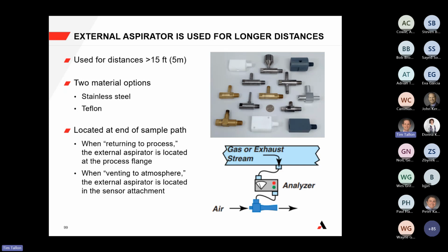And there's been a lot of people that have had CEM systems all around the world now, and they're used to doing some maintenance on the sample lines. It varies according to location how they clean it. Some people clean it with a variety of things like distilled water, even isopropyl alcohol or other chemicals. But that would be up to the site to decide what they want to use and what their concerns are.